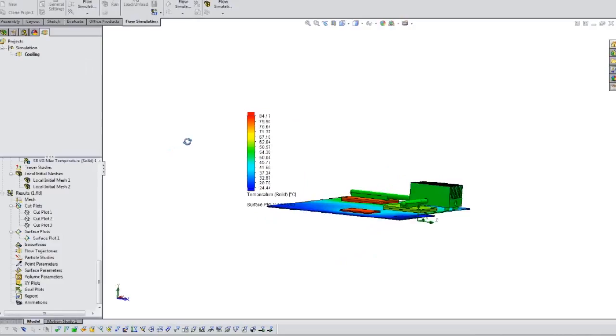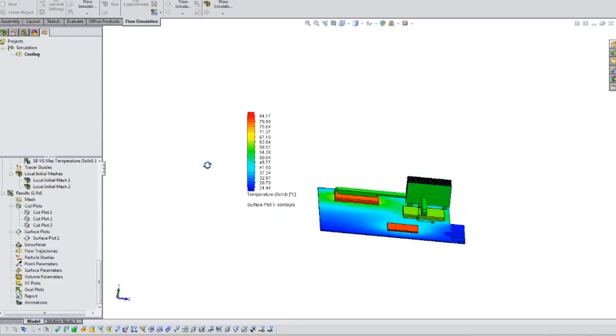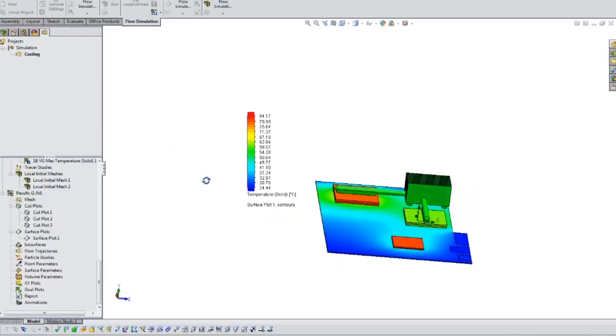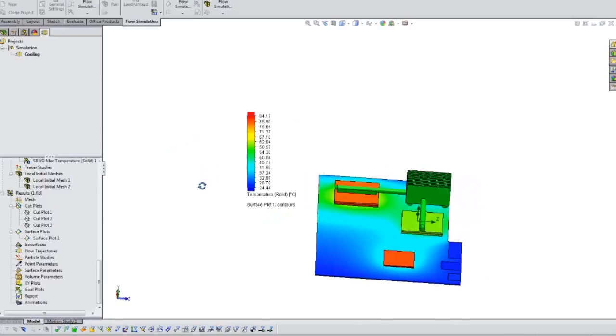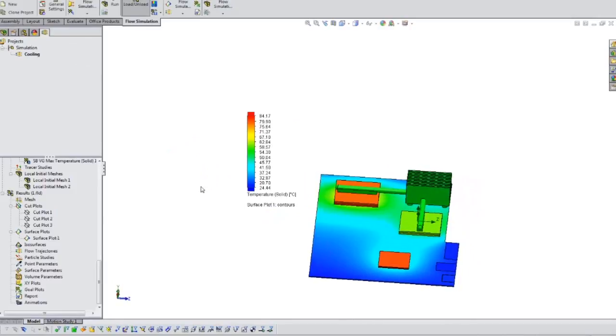Some of the other features I'll talk about that we use quite often when we're working with customers is, again, the goal plots, being able to export these to Excel really quickly. Go here and show you what happens. Again, it pulls all the data. These are all the parameters at the very end of the analysis. It allows you to take a look at what happened. You can see that for this mass flow rate, it started out as a value up here, and then it started converging towards the solution and flattened out. So pretty easy to pull the data out of the model.